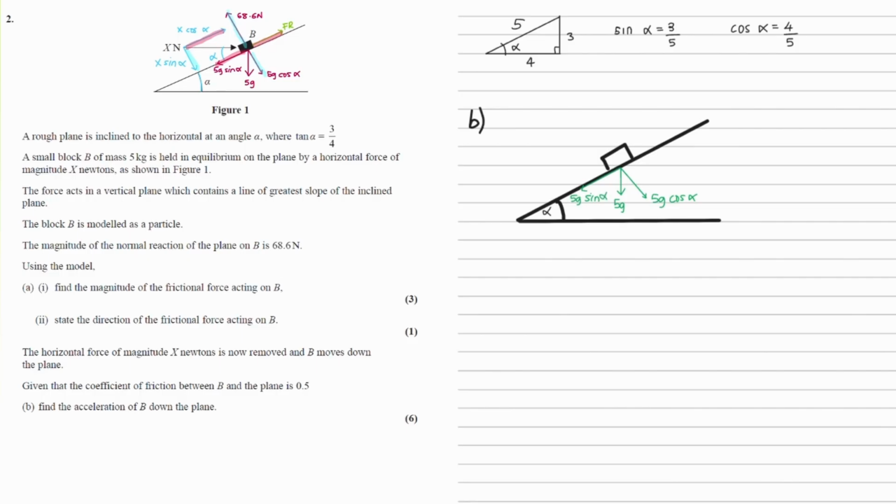Because the plane is sloping down, the particle would naturally move down the plane, which means the frictional force would act in the opposite direction, which would be up the plane. There would now be a new reaction force working there, R, and we can therefore show the particle accelerating down the plane.